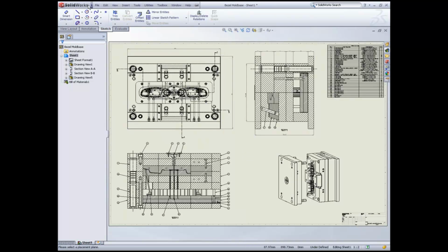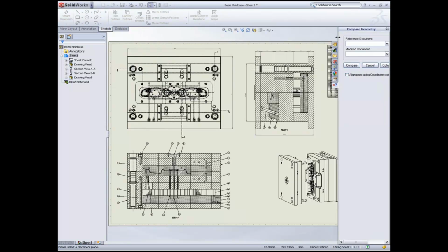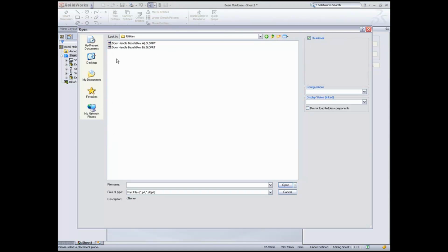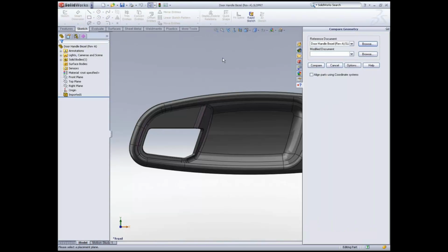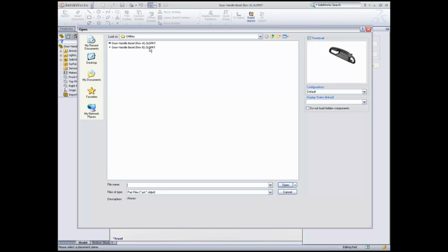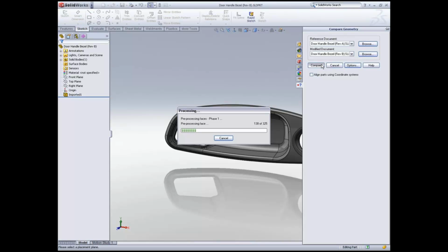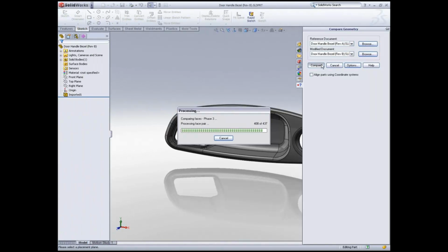In an ideal world, the customer would never change their mind. Unfortunately, they do. But fortunately, SOLIDWORKS has a number of tools to alleviate rework caused by drastic changes to the design. SOLIDWORKS utilities can be used to compare geometry between parts and accurately detail the differences between the two. By choosing two revisions of a part, each face is compared and color-coded to give an easy-to-read graphical feedback. This can take a couple of minutes to complete, but the results are worth the wait.